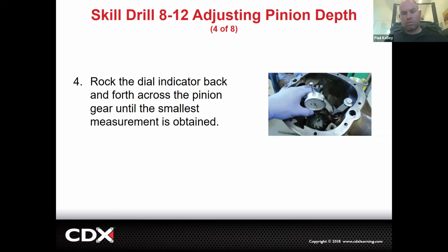But because where I came from, you can actually set this, but you have to have this special tool for this particular housing. It's not like a one size fits all. Like it's an SST for that differential housing. Let's say it's a Dana 44. You'd have this tool for Dana 44. You got Dana 44? I got the tool. Boom, boom, boom. I can measure pinion depth. Then you don't have to set it up and tear it down and set it up and tear it down. You measure this, you set it, you're good.